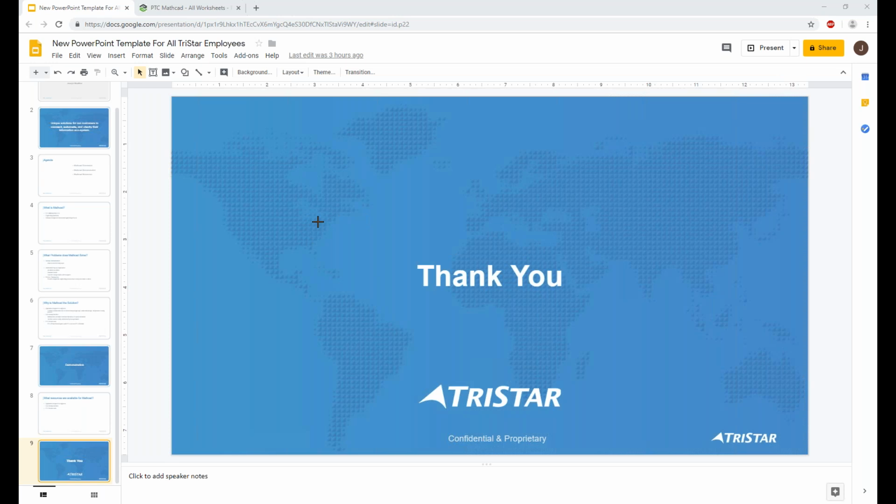How to integrate Mathcad in Creo? That is a good question. I do not have an example for you right now, but I can talk you through the process. It is very interesting. So you would have a Mathcad workbook. Within that Mathcad workbook, you would designate the variables that you would like to then transition or tie to your Creo model. And then within the Creo model, you would reference that Mathcad workbook and be able to define those variables. If that's a topic that interests you, I would love to demonstrate that for you, maybe a later date.